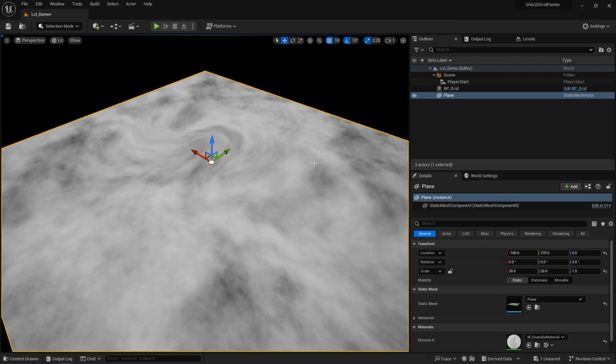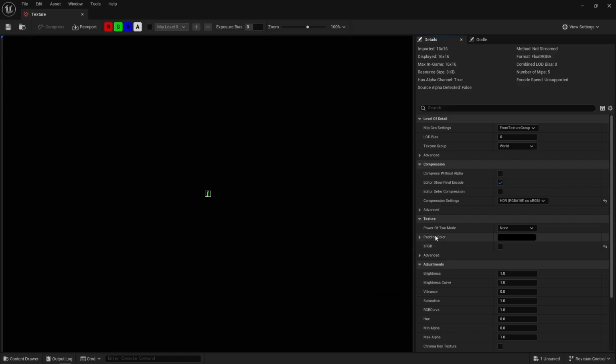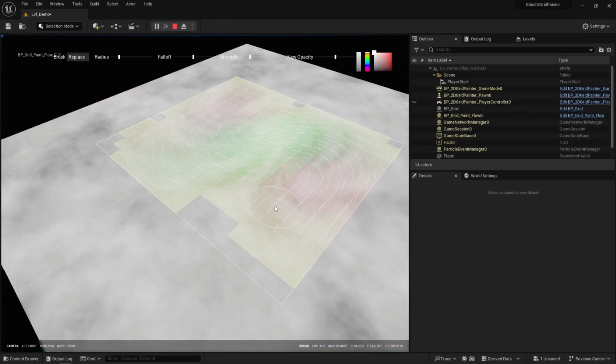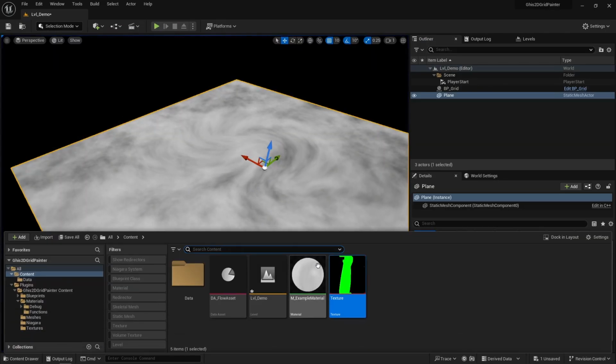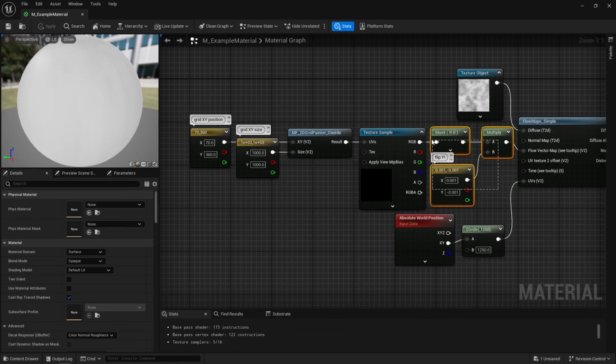Now that texture specifically could be used as a flow map, right? It's a 16-bit HDR texture, by the way, and what I painted on the grid is stored as is into the texture to keep the tool somewhat simple, meaning a negative flow direction is encoded as a negative number and the range isn't normalized, so there's no remapping to do to use that texture as a flow map.